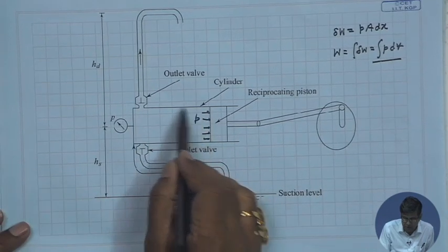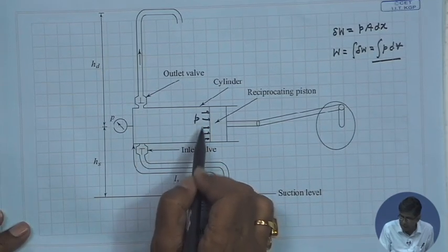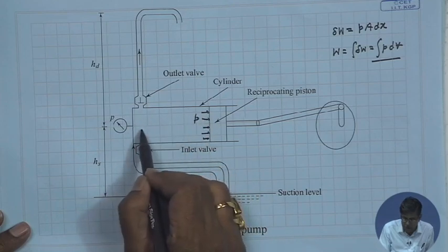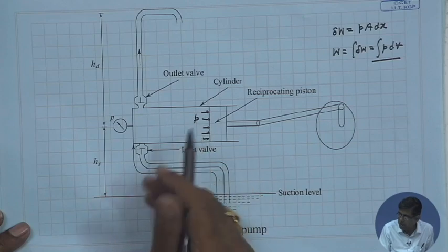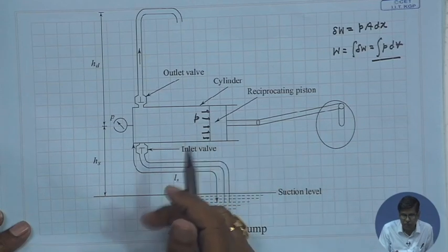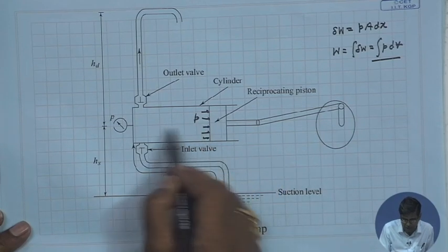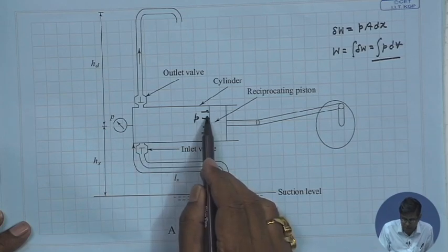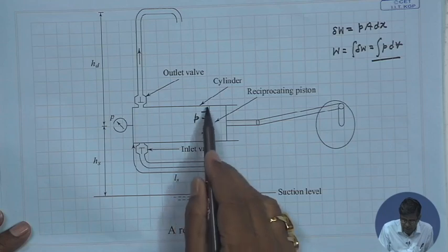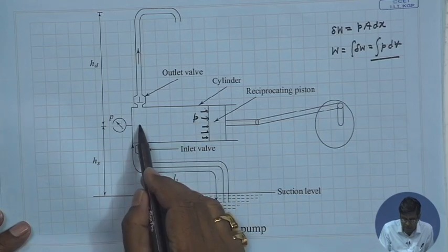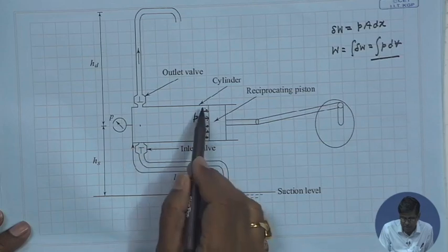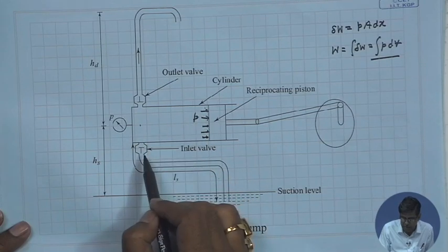In an ideally incompressible fluid, the travelling speed of the pressure wave in the fluid medium is almost infinite, very, very high. So, instantaneously it is sensed upstream, which means that any pushing here resulting in a rise in pressure will be sensed by the entire fluid in this cylinder, and that is the property of the incompressible fluid.